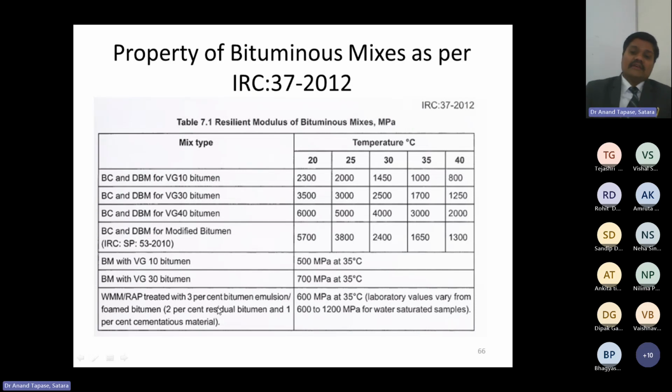It was the era of the last couple of decades in which we have worked on the use of plastic in road construction, use of rubber in road construction. Now the Indian Roads Congress has realized that many of the researchers have gone through this work rigorously, and they have found out that the bitumen is getting exhausted. The natural aggregates are getting exhausted. So there are a number of alternatives that can be partially added as a source in bituminous mixes.